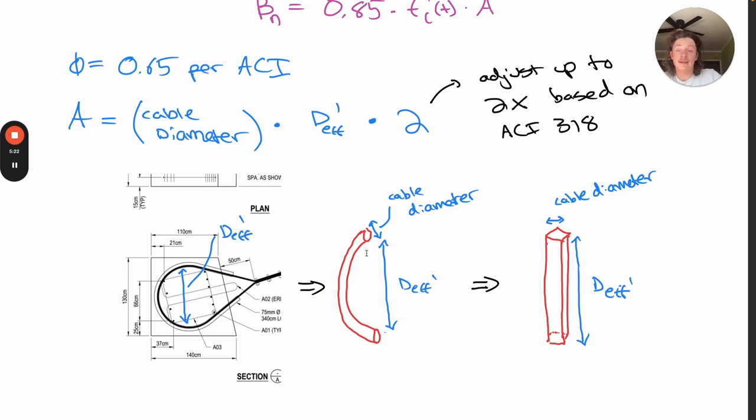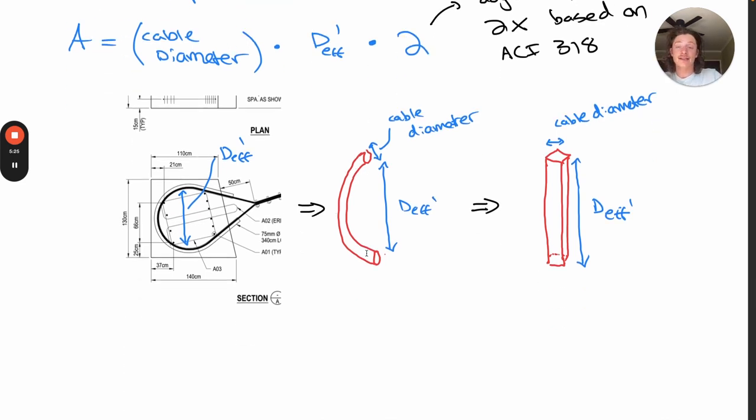So now that we've completed these checks, we can add a series of checks and flags that will trigger us to review the concrete strength calcs further if the demand exceeds capacity. If you're building this into a design tool, I would recommend building out all these equations and checks and making them a function of the variable t, of time in days, so that when you're on site, or if you're calculating how long it's going to take until you can hoist, or you can high hoist, or you can set sag, or you can begin decking, or how much material you need to be built on your abutments before you can do these things, it all can be a function of time.